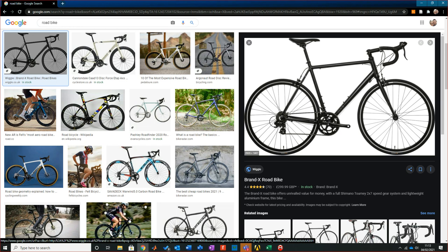So all they did is they said, right, what we'll do then is we'll take this section of the frame, we'll take the cross section, so this area here on the cross frame of the bike, and we'll simulate pulling that off and then calculating around its behavior and displacement. It seems dead straightforward. To calculate it is nice and straightforward, and in fact it's what we're going to do in just a second. But what they did is then built that in, and then they were able to start looking.